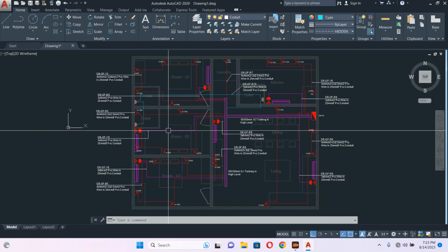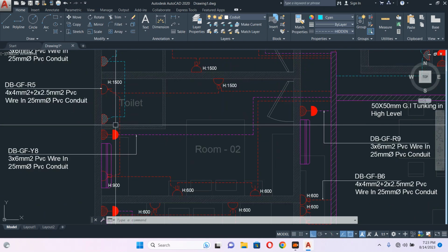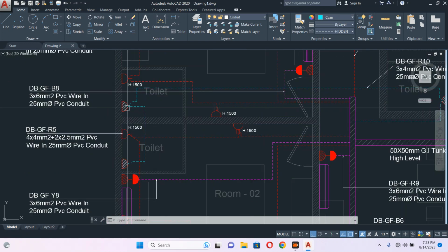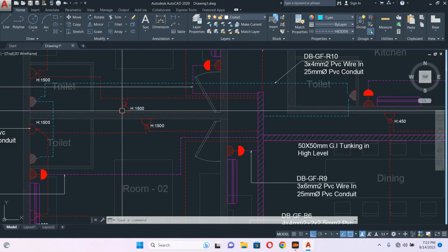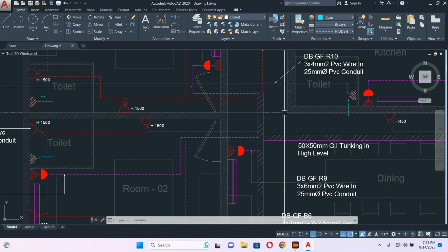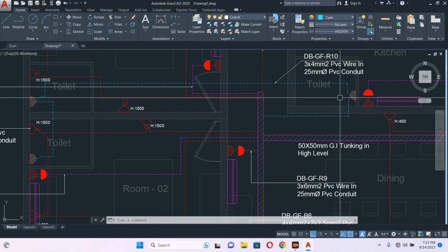Mostly we don't use it, but if there is an issue in some water area, you have to use ELCB. So this spare outlet is not a big current, so you can use 20 ampere, or you can also use 10 ampere, but 10 ampere is mostly used for the light only.